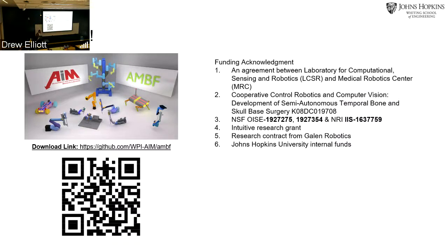Space robotics simulation, how easy is it to change the gravity? And is there any friction models for the sand that you have? The gravity is easy. You can change it by raw param, so you can set the world, or you can change that in the world description file. We have set it to, I think, 2 instead of 9.8, but you can change it dynamically. In terms of the friction model, the sand is not displaceable, so it's a fixed ground, but you can easily change the friction of the tires and the ground. And it's a combination of those two that gives you the traversal, and that is easy to change as well.